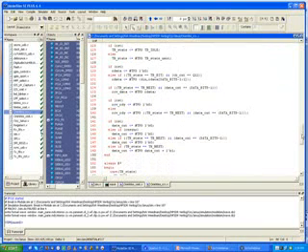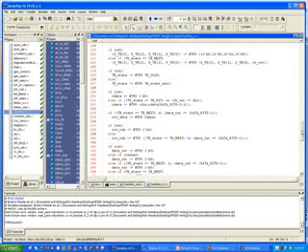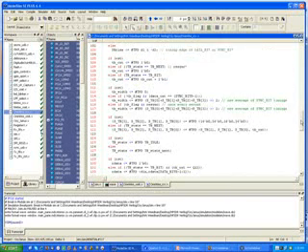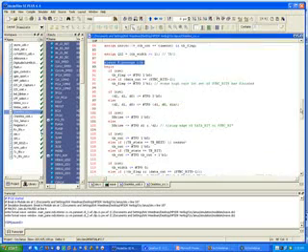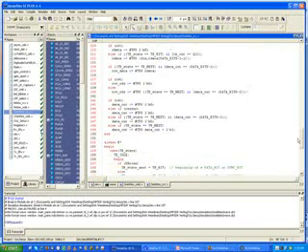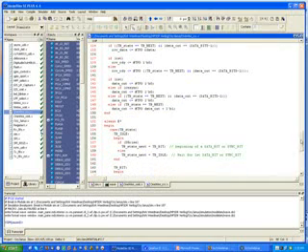So anyway, I have this block. And you'll notice that within this block I have different variables that I'm creating, and each of these are using non-blocking assignments. So that's the key, that these get turned into flip-flops, this basic structure. And like I said, we're going to cover more of this in the lab.